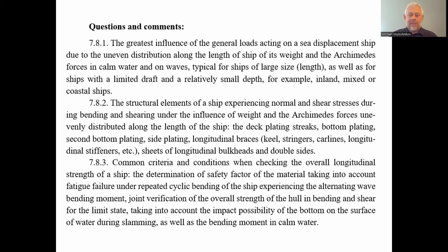So on the other hand, we either use the ballast in another peak relative to the load in the direction of the ship hull to keep the trim. This increases the bending moment and the shearing forces, and also increases the equivalent stresses when we check the strength by the criteria of strength. Or we do not use the ballast. So this reduces the magnitude of the bending moment and shearing stresses.